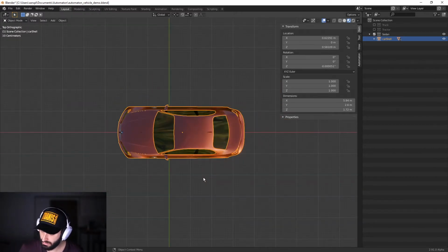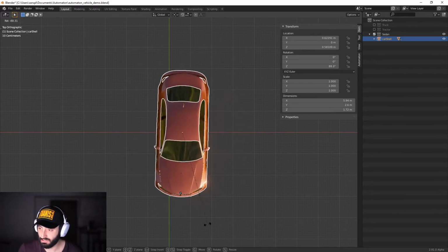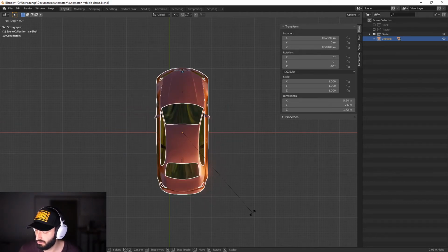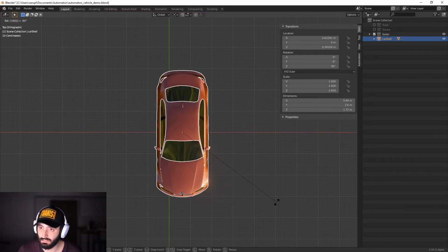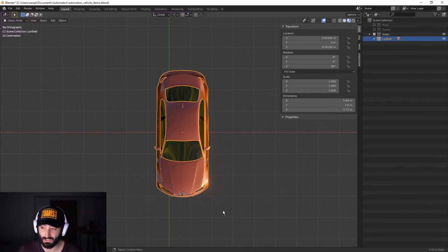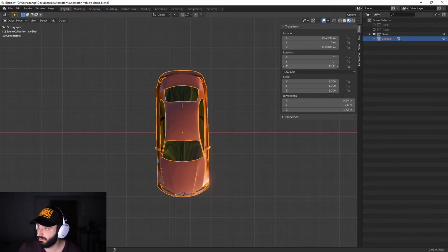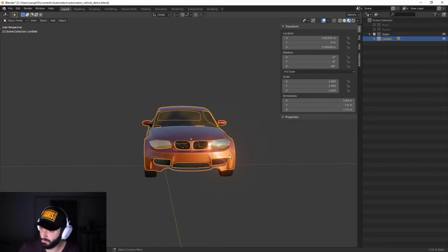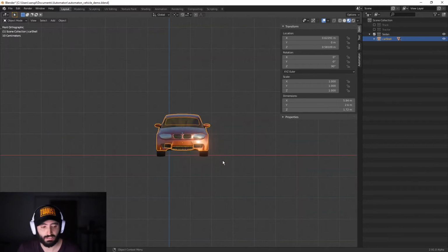So now I can go ahead and go into top view and hit R for rotation and rotate some 90 degrees. Actually should be, yeah, positive 90, negative 90 degrees rotation, but the actual set rotation of the object becomes 90. Anyway, you can add it right here in the numeric panel. Okay, after that, if we go to front view, we see that the object is now pointing towards us, but